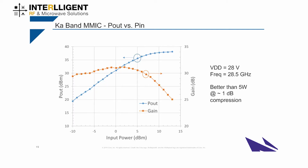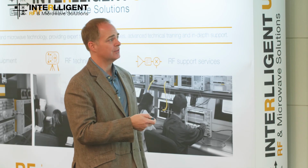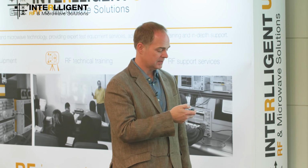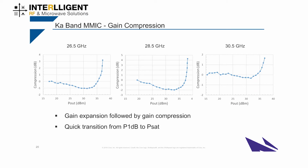So this is just a P in, P out measurement. You can see that at about 1 dB of compression, we're getting on the order of 37 and a half dBm of power, and we're still at about 29 dB of gain in this case. This was for the center frequency at 28.5. So better than 5 watts at 1 dB compression. And then similar compression curves across the frequency band. You can see that we do tend to get a little bit of gain expansion, which would be negative compression. And then once we get up to about the 37 dBm power level, we're at about 1 dB compression. A little bit better up at the mid band.